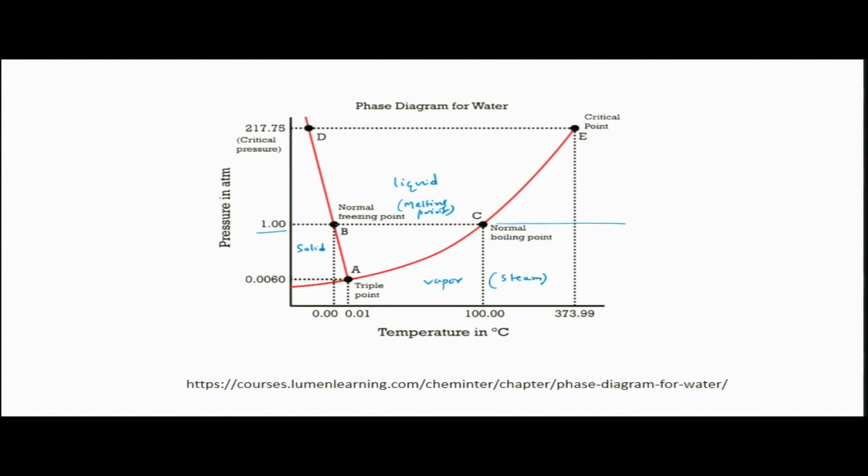Thermodynamic melting point and freezing point would differ a little bit when we try to practically see those kinds of situations. For example, during freezing, it does not freeze at that particular thermodynamic melting point, because when it freezes we need to create an interface, and because the solid is forming, that interface needs extra energy.